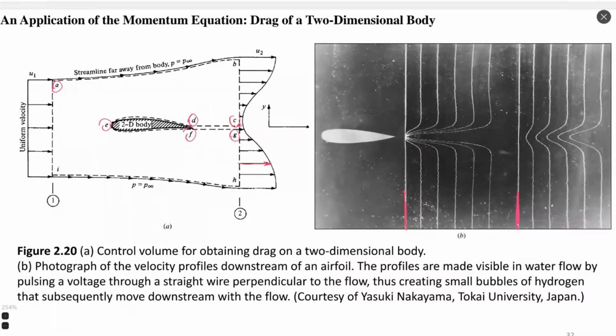Then FG has absolutely the same size and direction as CD, practically repeating this line. So CD goes in this direction, FG is the same line but going in the opposite direction. And physically, these lines CD and FG are on the same coordinate. So when we see the transition from one zone to another, we will not see anything because it has zero thickness. All the flow is joined through lines CD and FG. And after G, we have H, where we have a transition of flow due to interaction with the body.